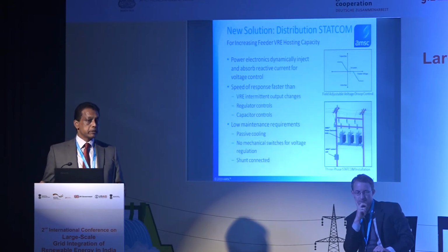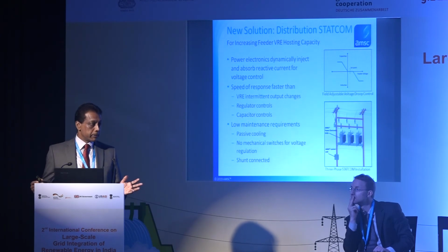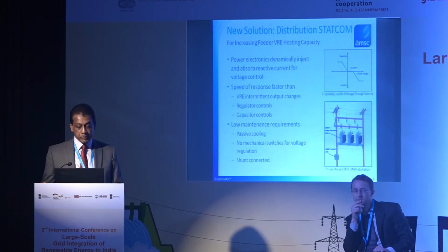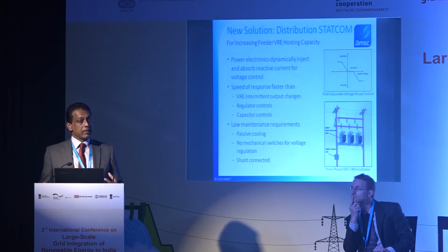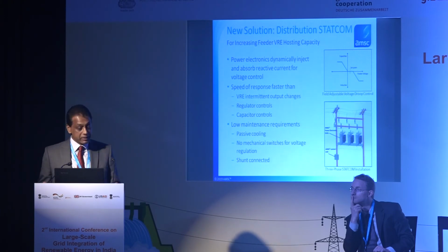Traditionally, STATCOMs and similarly SVCs, which are the FACTS devices as they are traditionally called, are large in size and applied in transmission systems. There are none installed at the distribution feeder level because there's a lot of infrastructure and a lot of controls that need to go with them. But what we've done is take that technology and bring it down to the distribution feeder level, and what we call a deployable 1 megavar or half megavar STATCOM system that we have developed. A picture of it is shown here, and I'll show you an installation picture later as well.